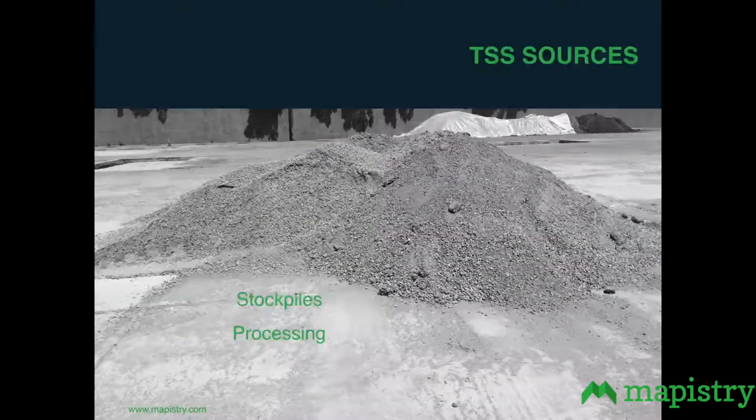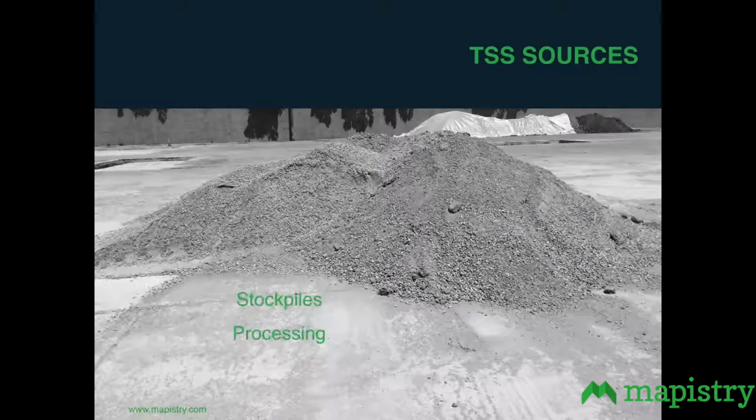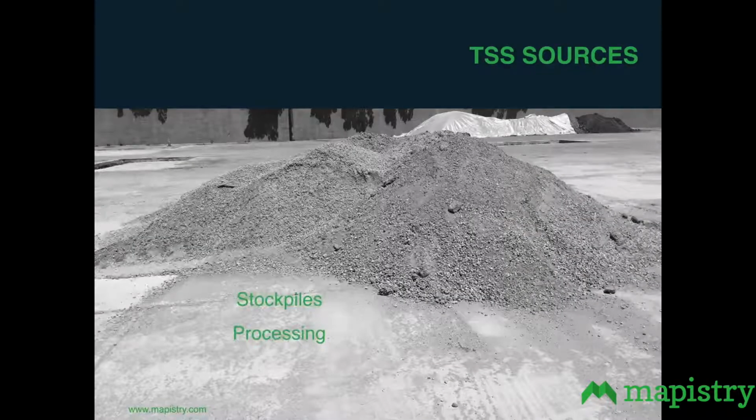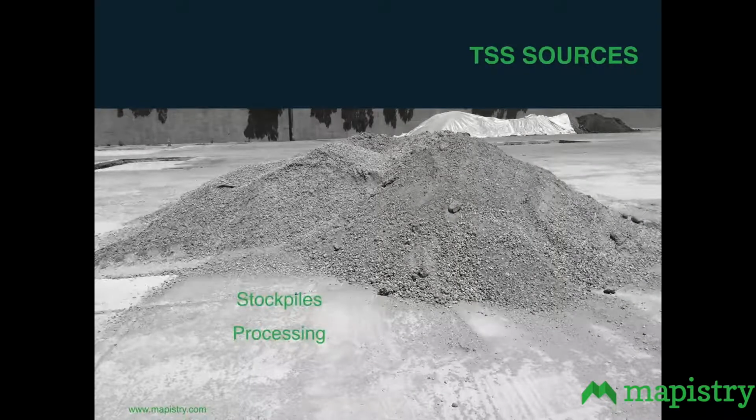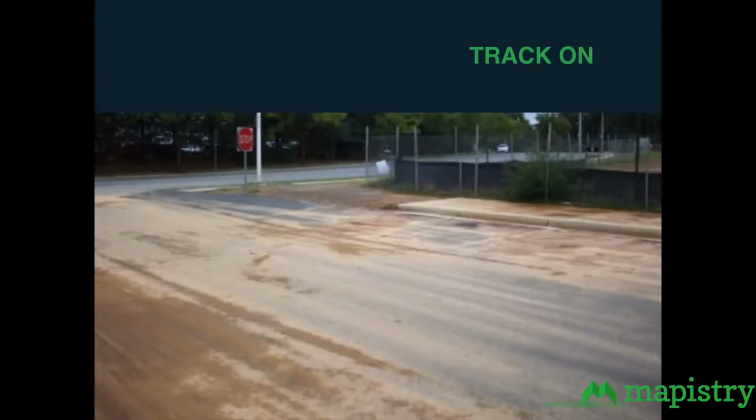Sources on site: maybe you have construction going on at your site, maybe this is an industrial activity for you, processing of materials, graded road base here, any kind of stockpiles that could potentially be contributing to your TSS. This is a glaring source: hard surface, uncovered, no berm, no filter around it, a big source of TSS on a site.